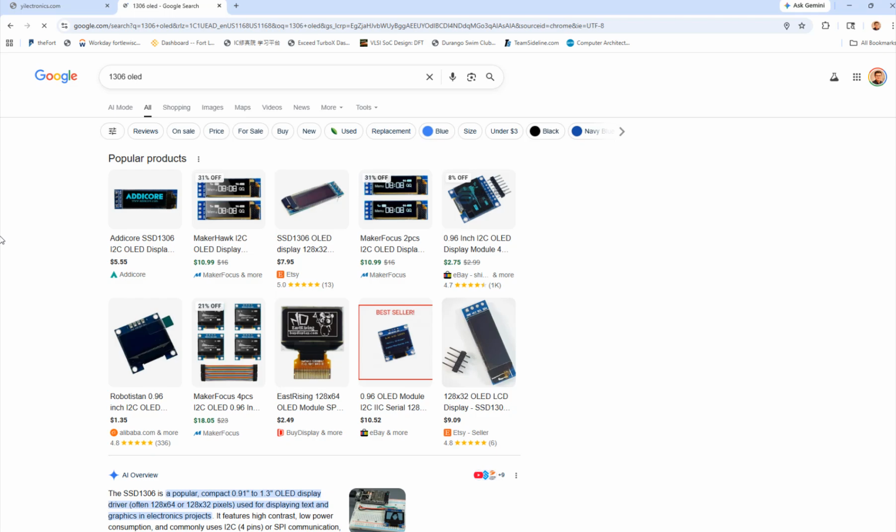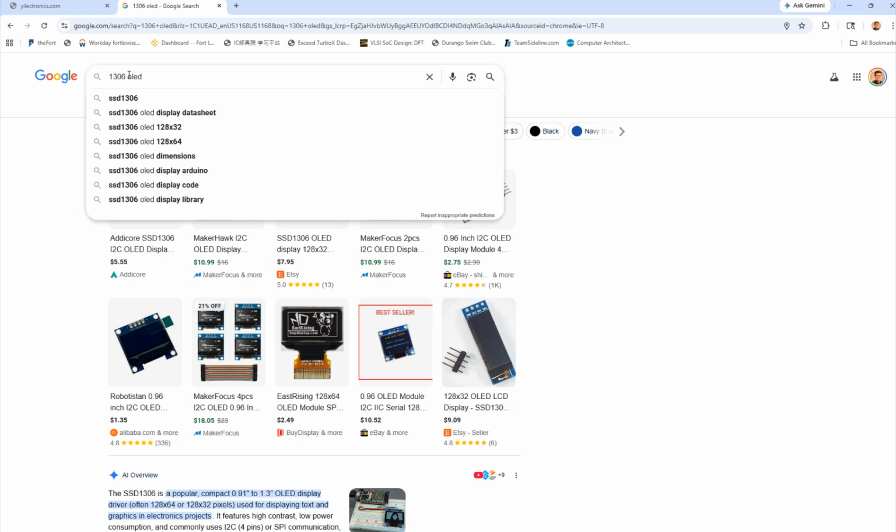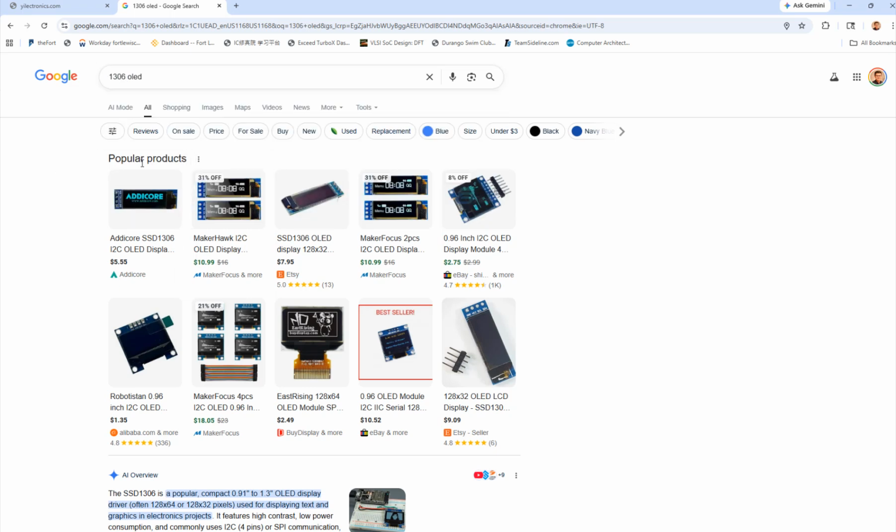All right. So the 1306 OLED is very popular. It's low cost. The 1306 means it's a control chip, a display driver chip being used for the display. So the display module integrated a lot of things. I don't know the circuit because it's packaged, so I couldn't see anything inside. But we know it's a 1306. If you search for 1306, you can see the data sheet, you can see the timing, and they do have different versions. Some of them are I2C, and in the past we used a lot of the I2C versions communicating with Arduinos. It's really simple.